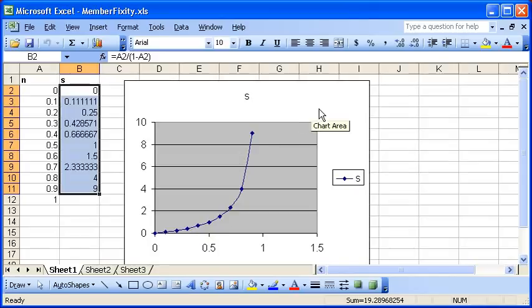However, remember that the relationship between moment and member stiffness is also a nonlinear one. So if you were to plot a similar graph with the variation of moment at the ends of the member with this variation of stiffness, you'd find that it's slightly nonlinear, but only slightly. So this is actually quite an effective way to define the proportion of stiffness that carries over across the spring.